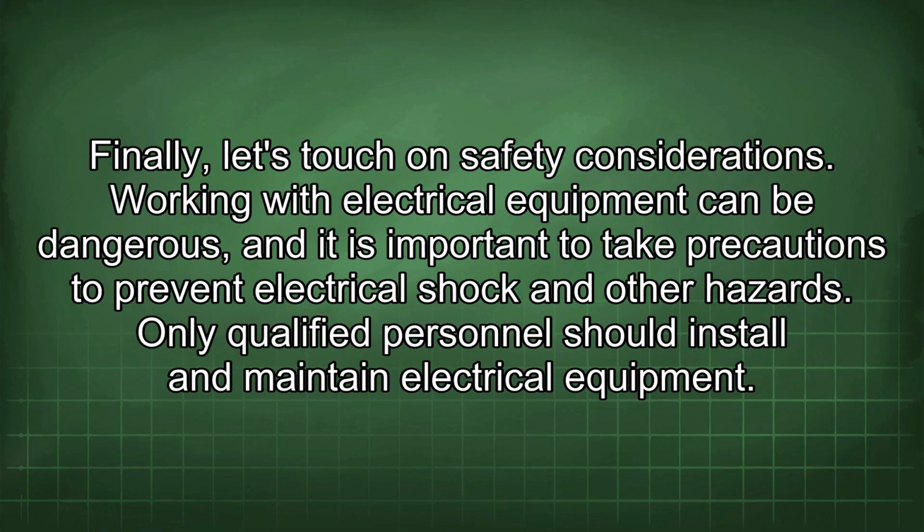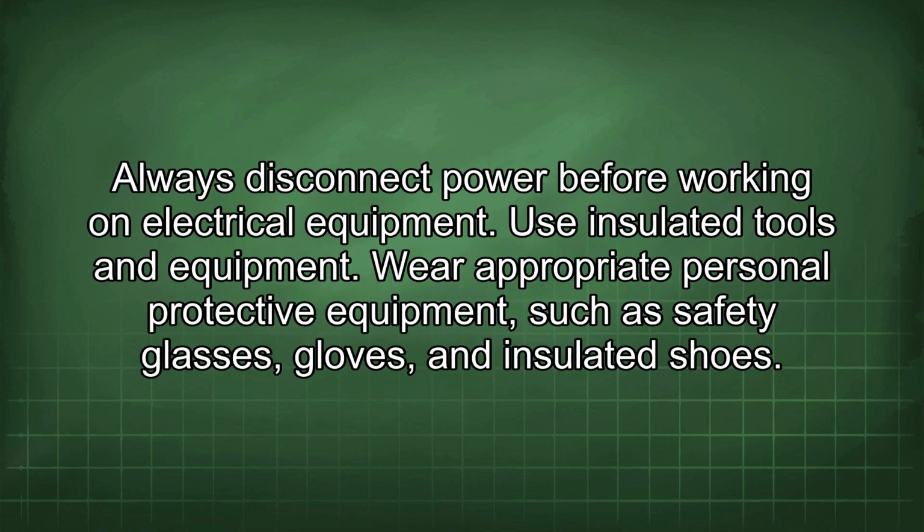Finally, let's touch on safety considerations. Working with electrical equipment can be dangerous, and it is important to take precautions to prevent electrical shock and other hazards. Only qualified personnel should install and maintain electrical equipment. Always disconnect power before working on electrical equipment. Use insulated tools and equipment.